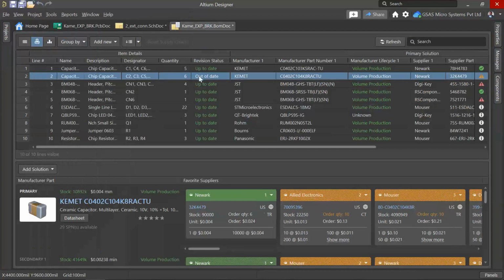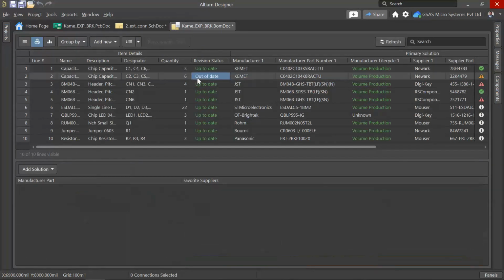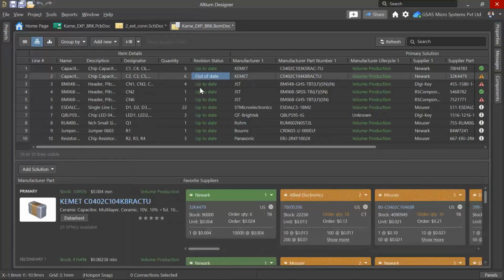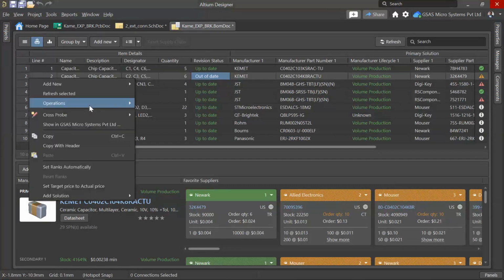But this Active BOM check will let you verify the component revision status if your component is posted on the cloud. That means posted components if you use in your schematics. That is very important. Simply posting the component won't work. If you use the posted components on the cloud in your schematics, it will verify the revision status as well. Now let us make it the latest version.